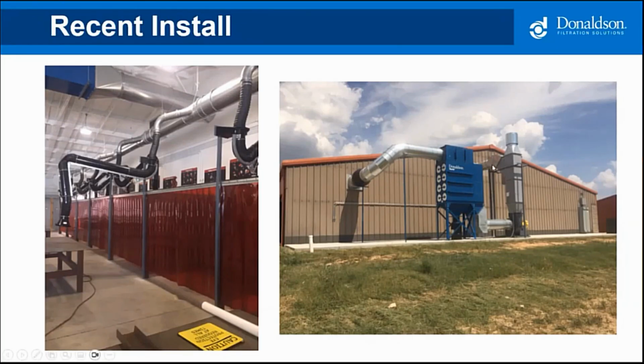In this case, we return the air back in, or we have the option to exhaust the air out the stack. This is a summer-winter diverter valve. In this case, the school would heat in the winter, and you don't want to throw the heated air out and have to make it up, so we recirculate that back in. In the summer, they don't have air conditioning, so they pull the clean air through the open doors and send the filtered clean air straight out of the collector.